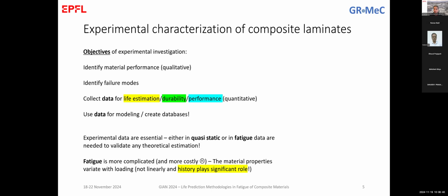And this complexity of the testing, of course, on paper, doesn't complicate things. But in reality, if you add one parameter, it might be that you have to repeat a complete SN curve. And to make an SN curve, a complete Wöhler curve, what we discussed yesterday, you might need more than 15, 20 days. So imagine another curve means another 20 days and so on.